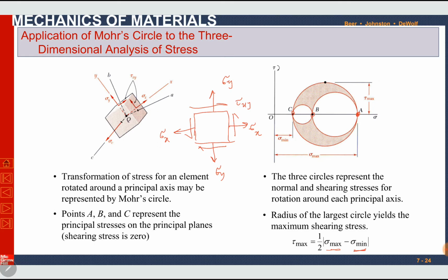Similar to the previous methods, using Mohr circle or using formulas, you can find sigma a and sigma b, or sigma maximum and sigma minimum. Once we find sigma a and sigma b, we can draw their circle anywhere. You must know that this is sigma a or sigma b, or sigma minimum and sigma maximum. Sigma c in plane stress element is always 0, so it will be here. So we know the second circle will be here, it will be a dotted one, and the third will always be around the two